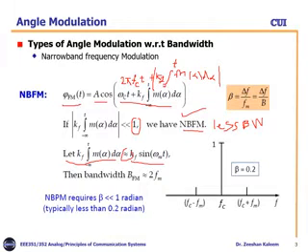In this case, the bandwidth of the FM signal will be approximately equal to 2fm or 2B, because this is the message signal bandwidth. We can see that from the spectrum: this is our carrier frequency, and this is fc plus fm and fc minus fm. So the total bandwidth here will be 2fm or 2B. This will be the bandwidth.